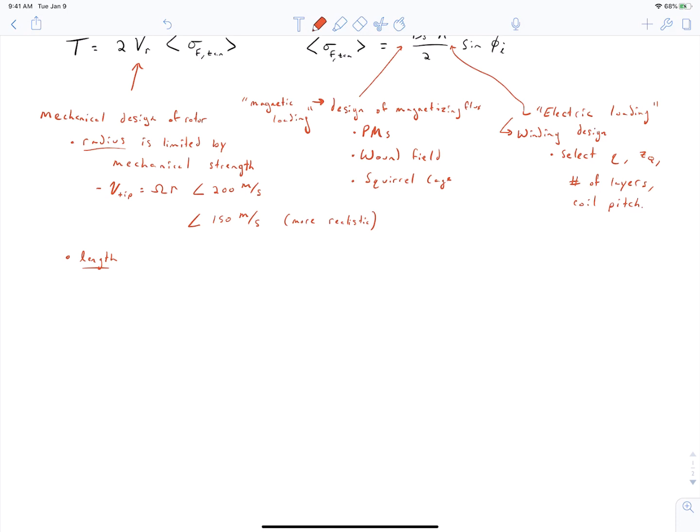And again, that's only a typical case. Of course, there are designs where rotors will go into the critical speeds and maybe even operate above flexible bending modes. But a crude rule of thumb is that you design your rotor to have a short enough shaft length so that you stay below your critical speeds for your entire operating range.